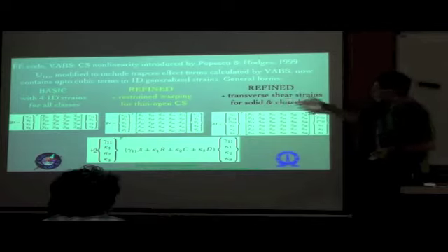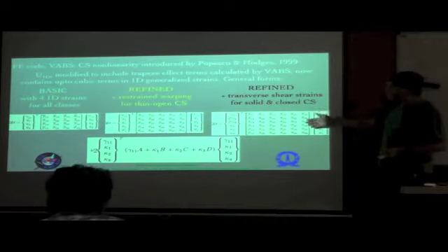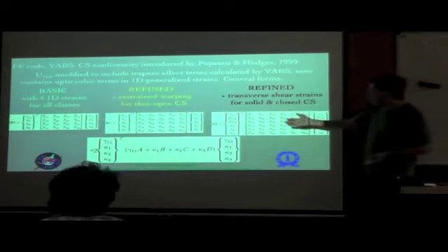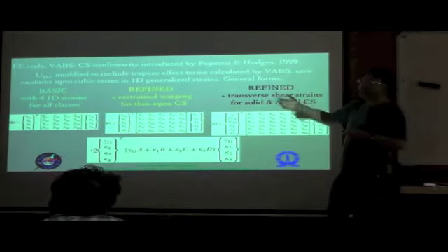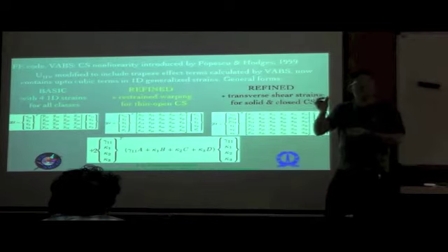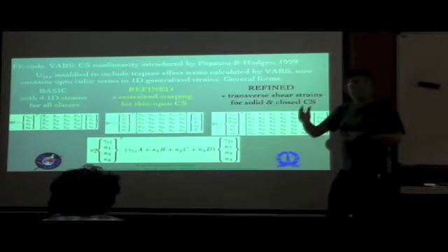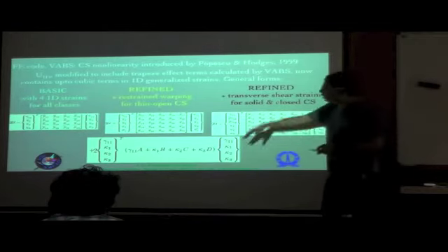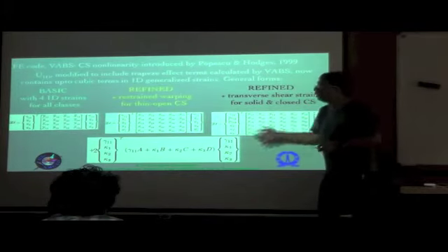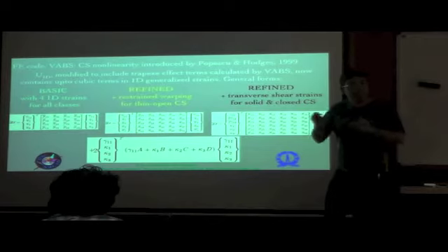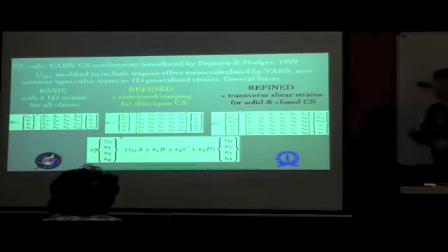But in each one of these three, if the nonlinearity becomes important, then you basically add this set. Or in other words, in a finite element kind of an implementation in the software, you can set a flag, and you can either set that flag to be true or false depending upon whether you want the nonlinear terms to be included or not included, depending upon the specific kind of configuration that you are looking at.